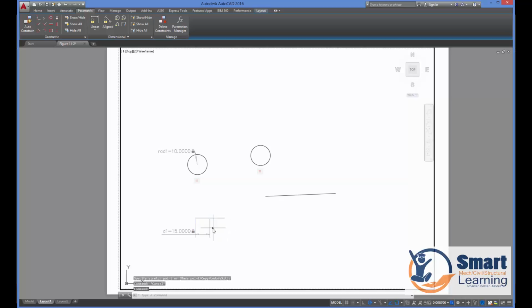And this is, I think, the central distance, so we have to carefully select this linear. I picked the midpoint, I think, this 30. So now you can select this object and select this object, and they will be equal. But here you can see this object is horizontal, but this is not horizontal. But if you measure, the distances are the same. So that is the intention behind this equal symbol.